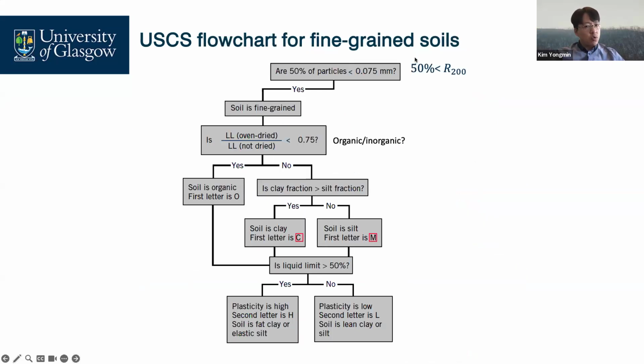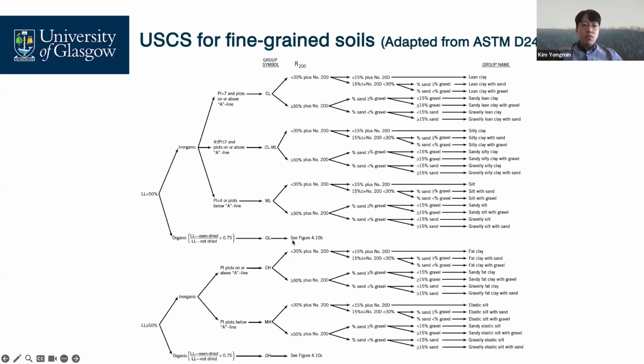And these are fine grained soils. In the fine grained soils, we need Atterberg limit results, liquid limits, and even the plasticity index. Laterally, we can see something like that. Okay, Singapore clay is something like, for example, sandy clay with gravel, or silty clay.